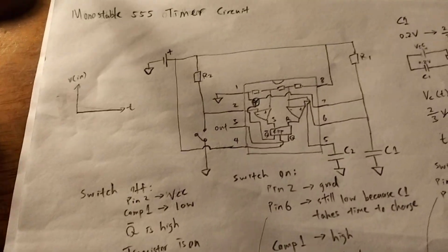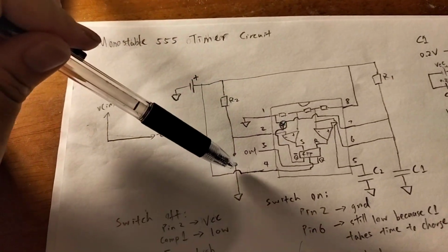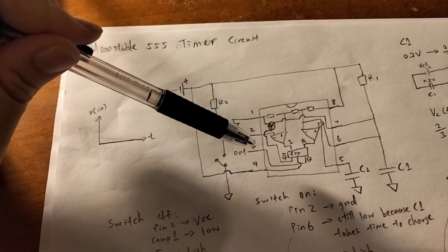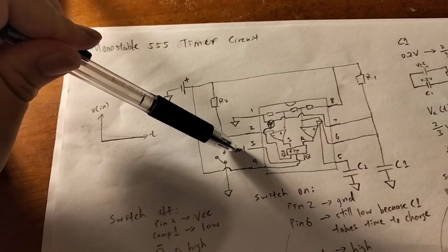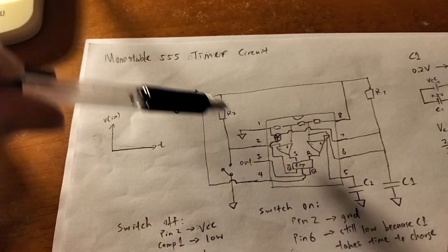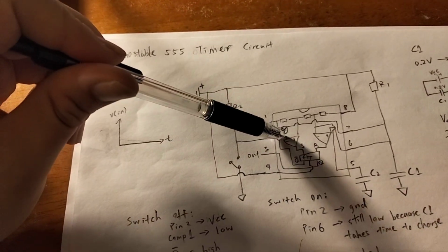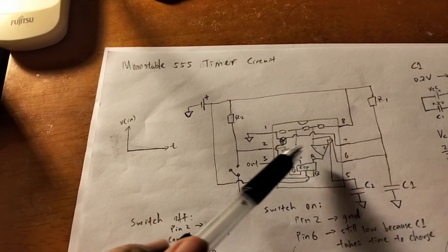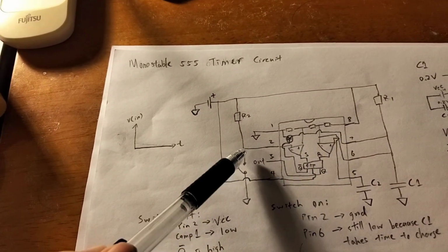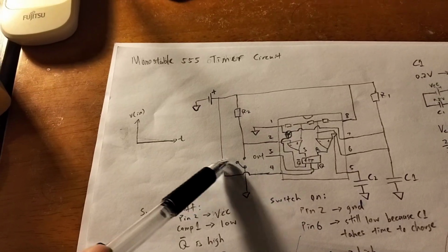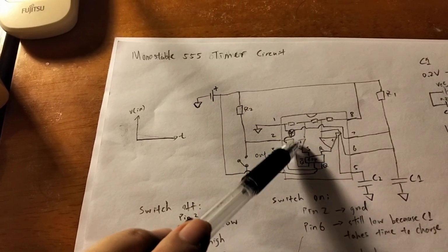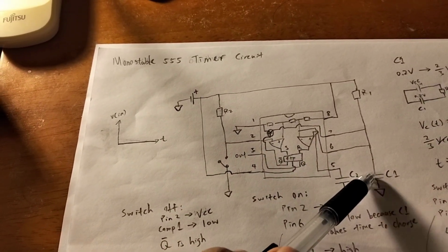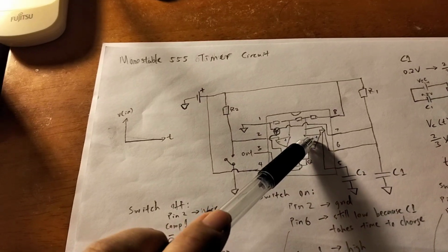So why does that happen? First of all, why is it that after 10 seconds of holding the switch, the out is still on? The LED still lights. The reason is that at that stage, both of these comparators are outputting high. Because we haven't let go of the switch, this comparator outputs high. And then the timer has finished on this capacitor, so this comparator also outputs high.